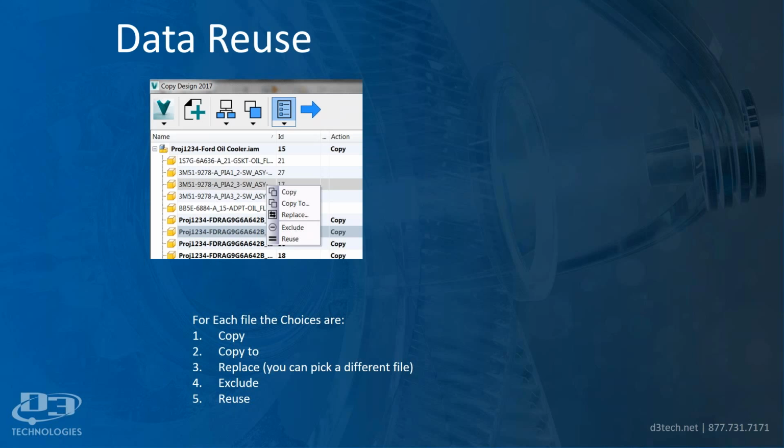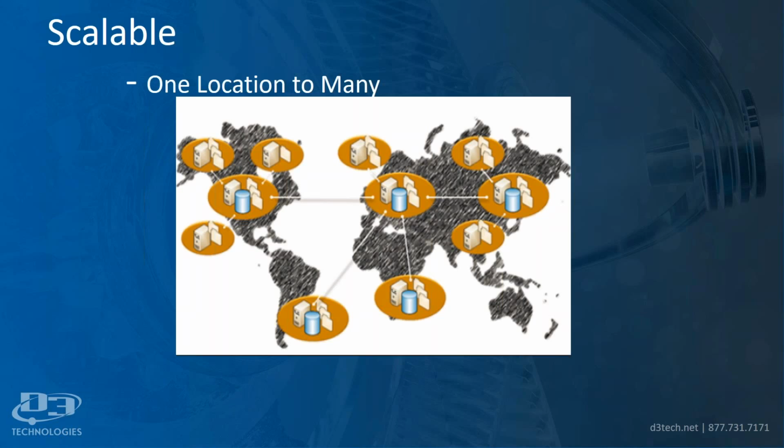All right, well, I'm going to go over to the next topic then. So scalable. Autodesk Vault is very scalable. We can set up your Vault. If you have a small shop, we can set up a single site where the Autodesk data management server, file store, and database is on one server. Or maybe your company is regional. Say your company has multiple branches in Texas. We can set up a replication of just the file store and have the database on the publishing site. So the file store is being replicated throughout maybe 3 or 4 different sites in the state of Texas.